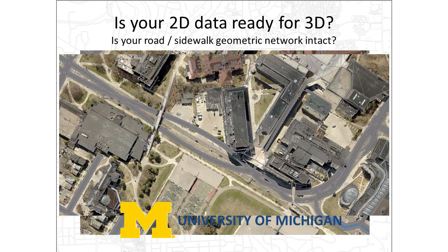Now it's hard to tell with this, but there's a lot of diagonal lines in here on the items that came in from PLW. That is not a PLW artifact. That is lines that are being put in by CityEngine, and it took us quite a while to figure out how to get rid of them. There is a tool for model cleanup that can get rid of some of those lines, but you really don't want to use that for cleaning up the diagonals here. There is a script out on GeoNet that will take them out 100% and clean them up so that they don't show through. But we had a hard time finding that at first, and if anybody's run into that issue, send me an email and we'll send you the script for it.